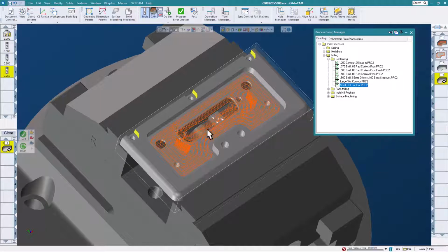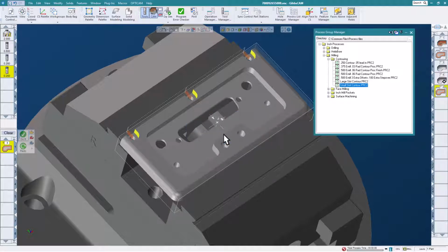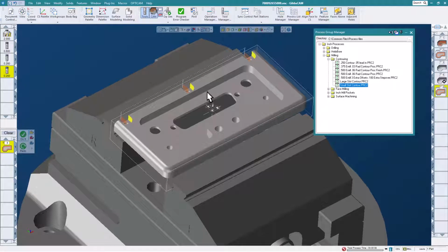So I have something called a small slot contour, and we'll say do that. And again, I use the slice body to give me analytics tool paths. So, you know, it's a bit cleaner tool path, or I shouldn't say that it's a cleaner toolpath. The G code is a bit less because we're using lines and arcs. Okay, so far so good.